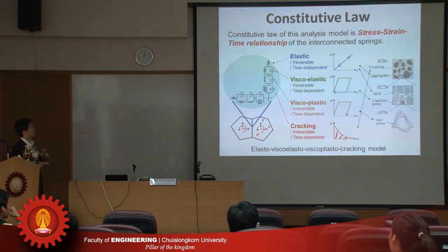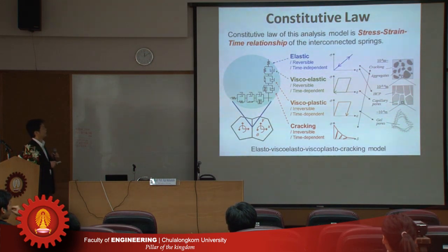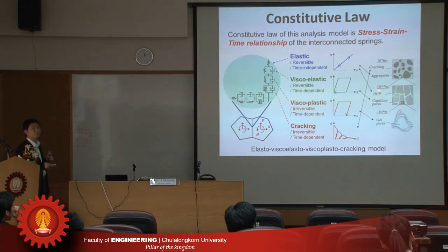In both normal and shear directions, this mechanical model is introduced in my model. This model is composed of four components. The first one is elastic strain, the others are viscoelastic strain and viscoplastic strain, and the last one is cracking strain. Each component represents one part of the material at the microscopic level.